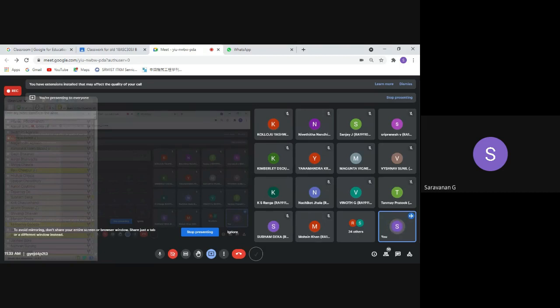So C star and CF will not be there in your aerodynamics, but the area expansion ratio and mass flow rate will be there. C star and CF are our performance parameters for the rocket system. That is the additional topic you want to do by substituting the same m dot and the same relation of kinetic equation and the other things. You can use it and get the relation for characteristic velocity and thrust coefficient. So it's better to go and take paper and start to solve the expression for area expansion ratio first, mass flow rate second, and thrust coefficient third.